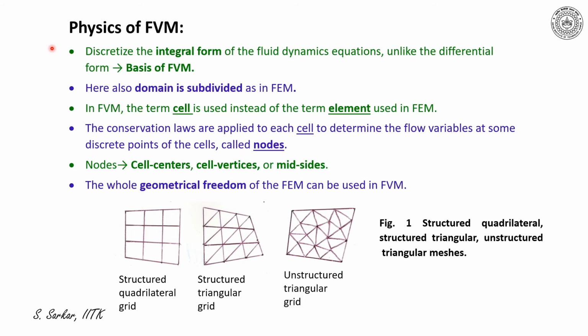What I have explained so far, I have summarized under the title Physics of FVM. The discretized integral form of fluid dynamics equations, unlike the differential form, would be used in FVM, which is the basis of the method.